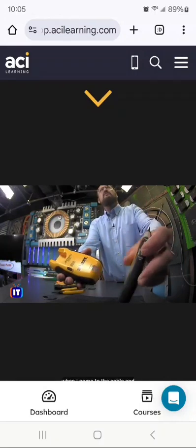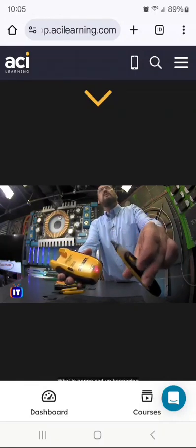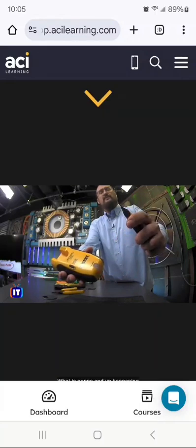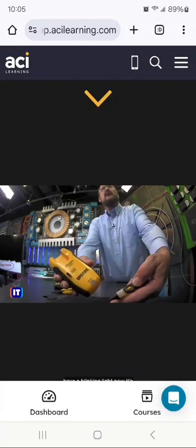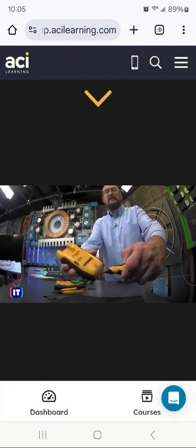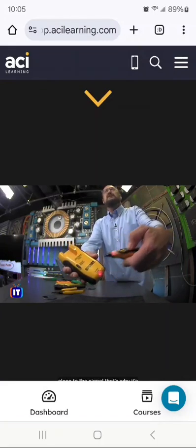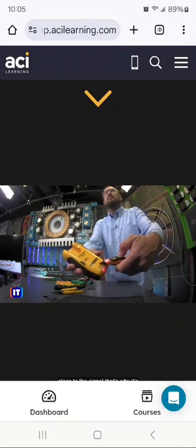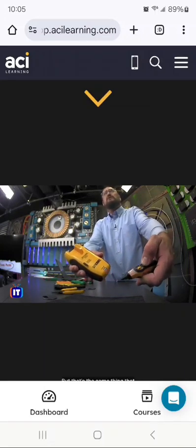And when I come to the cable and it locates the appropriate cable, hopefully we're going to see that we have a blinking light. Now, let's do transparency here. It's generating the signal, and because I'm so close to the signal, that's why it's detecting. And notice as I get away. But that's the same thing that would happen in your server closet.